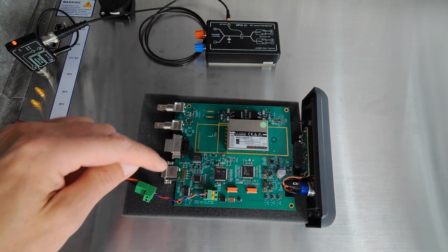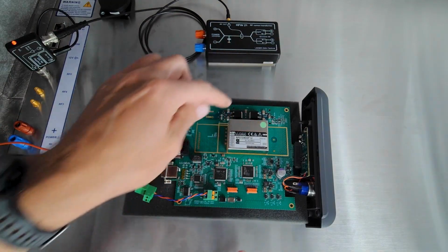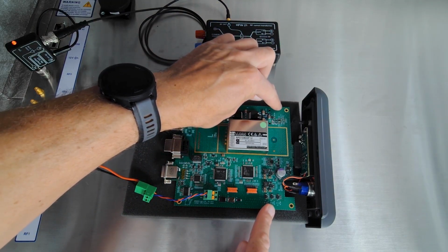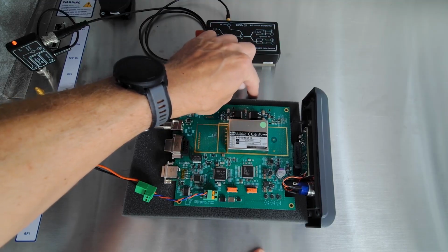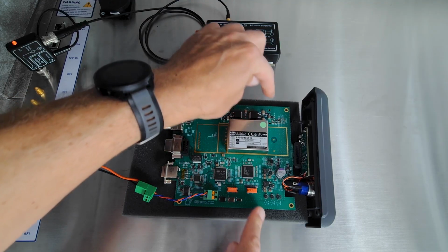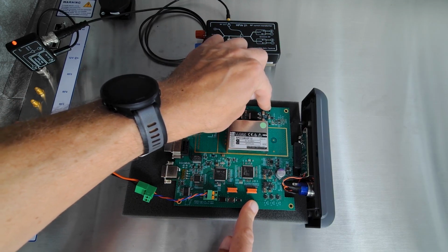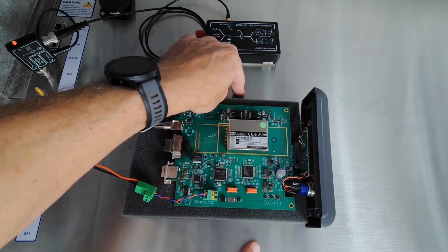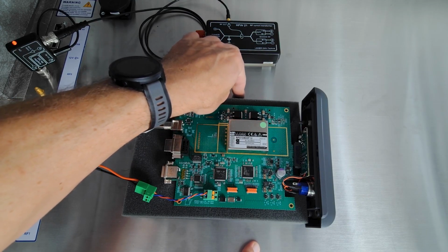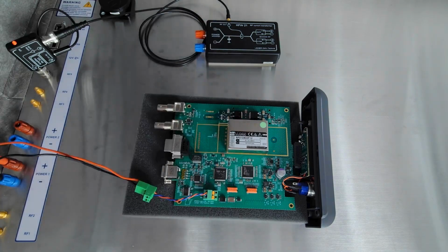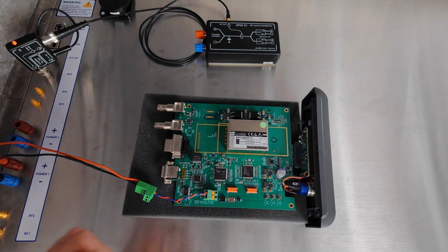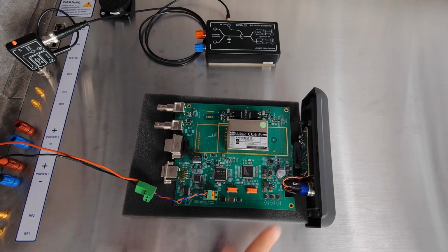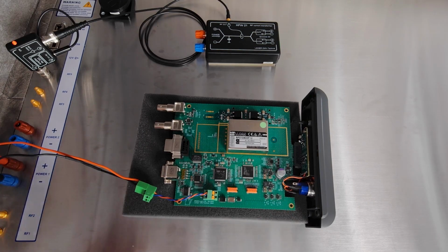Now for this measurement, we have to connect the ground of the main PCB with our reference plane, so that between this plate or this plane here, this PCB, and our plane, we get no more voltage differences for our measurement. And for that, we use some copper tape. I have here these holes in the PCB, which are connected to the internal ground.